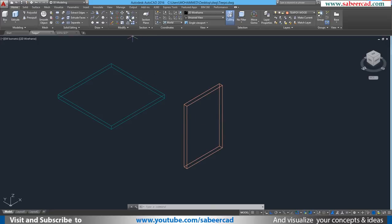Next, I'll go for a rotate command. Click on rotate. When you're asked to select the objects to be rotated, type the letter L. You know that when you give L at the select object prompt, you refer the most recently created object. So that particular object got selected. Then just give one more enter for confirmation.